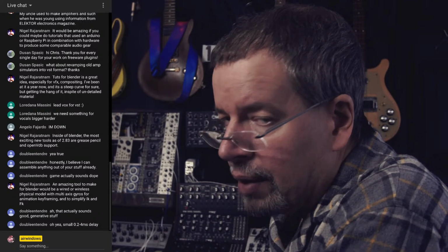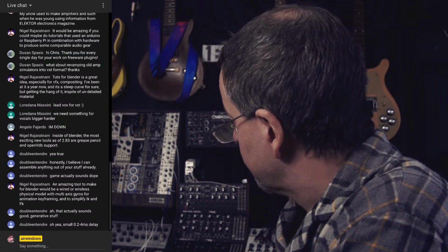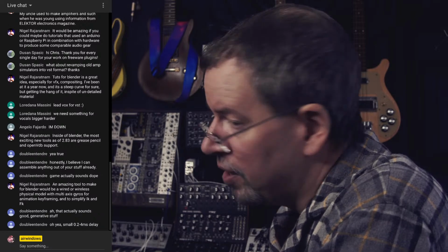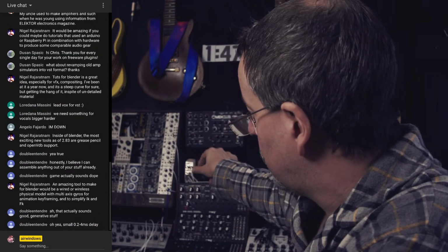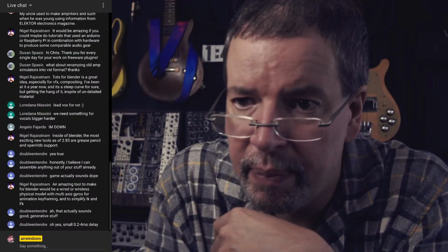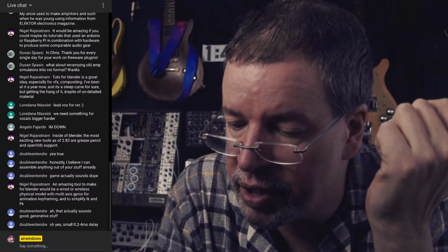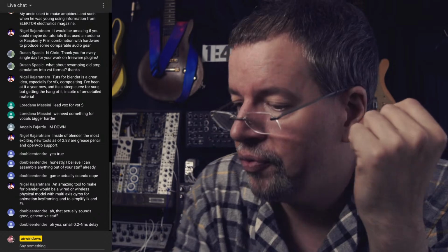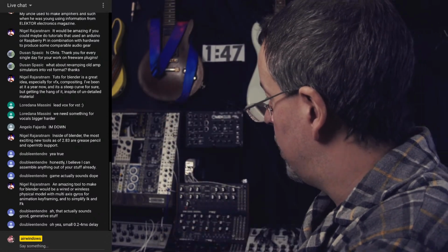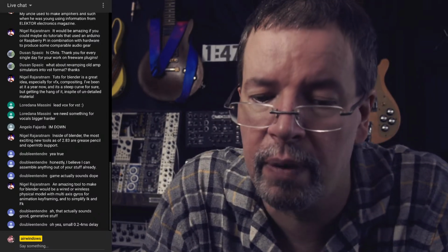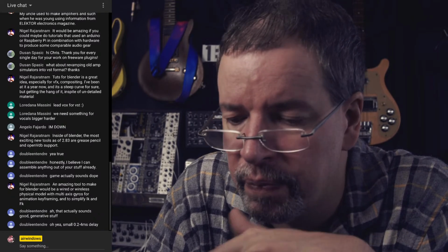Here's one of the things that I was doing. The last couple of times I've played, I've patched the Turing machines into each other in a new way. There is a CV control, and the CV control offsets the voltage that is set by the large knob. What that means is, if I'm understanding what it's doing, which I think I am, if the voltage is high on the CV, it turns it clockwise more, which means that from occasionally changing the pattern, it can go to never changing the pattern.